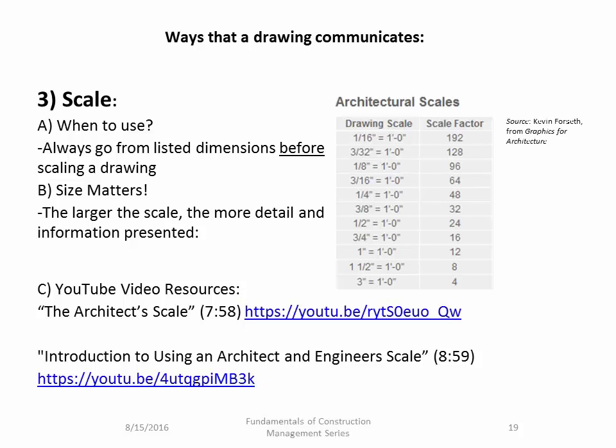Often drawings will have the 3 inches equals 1 foot reduced down to 1.5 inches equals 1 foot, going all the way down to quarter inch scale, where 1/4 inch equals 1 foot, where you have a 48th of the size of the actual object that you might be looking at in person. You're drawing it on the page so you can fit it onto a page.